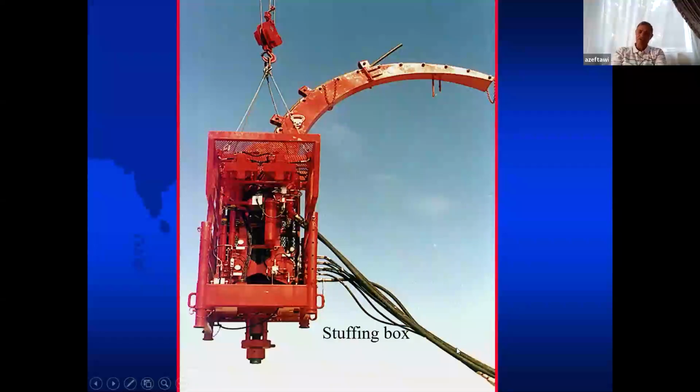The weight of the hydraulic hoses and the weight of the hydraulic oil inside them is on these connections. This connection is not designed to withstand load. It is to connect only. So now, since they used them to withstand loads, all these connections are in question now.